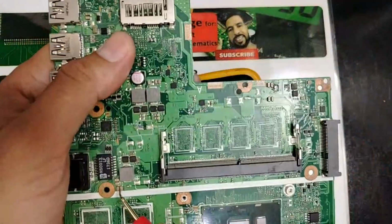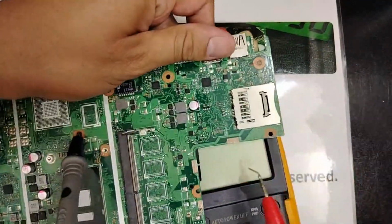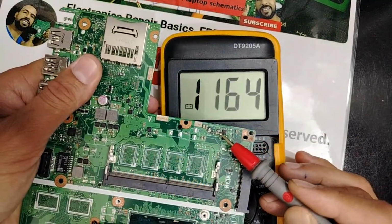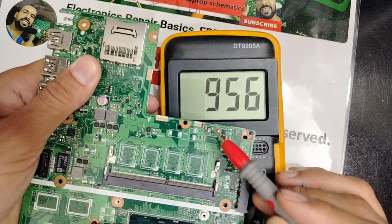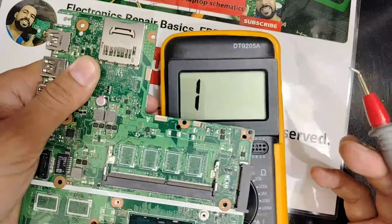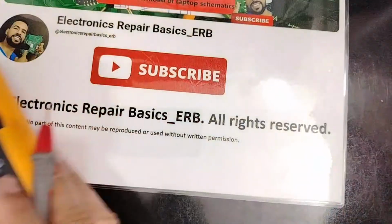Let's check this one, my friend. Okay, let's check those here. Okay, basically, those are for 3.3 volt. So, once we get 9 here, it means these ceramic capacitors are not shorted, my friend. I should not remove them. These capacitors are not shorted. Where is the schematic?